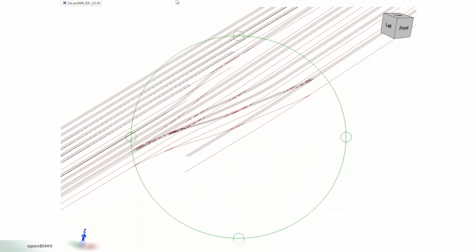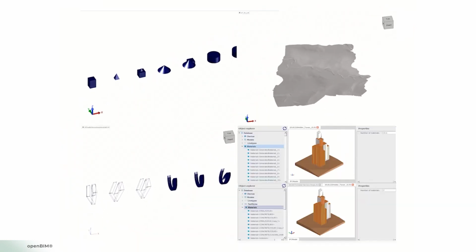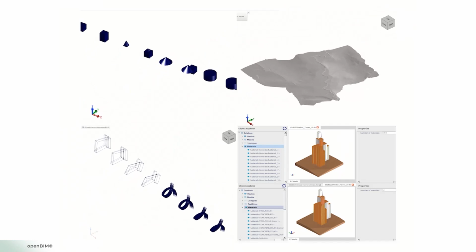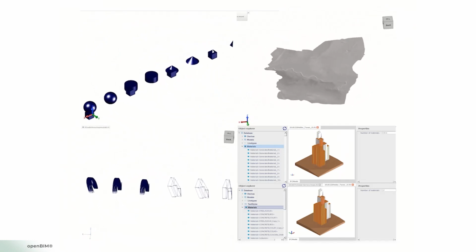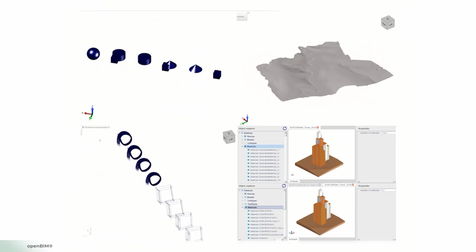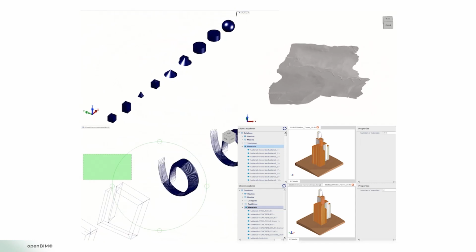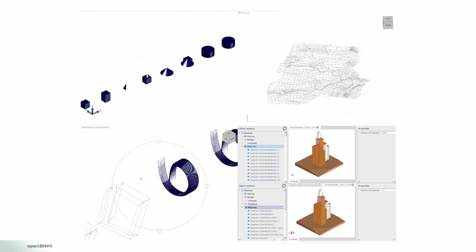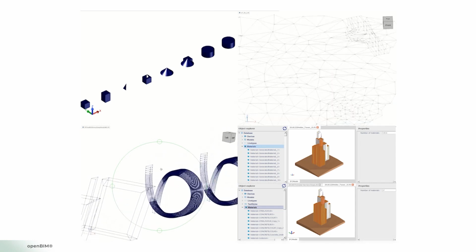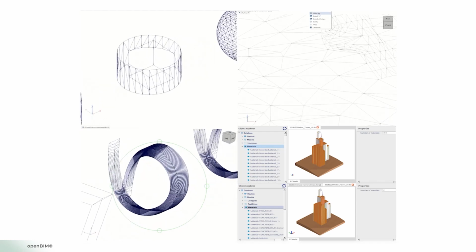These new types of curves are mainly used in road and rail design. We also implemented support for several geometrical entities as IFC CSG primitives for the special ACIS modeler and IFC triangulated irregular network, which is typically used for terrain representations in recent IFC schemas. We implemented a new sweep operation for the ODA facet modeler. So Facet Modeler now supports the full set of modeling operations required for IFC.